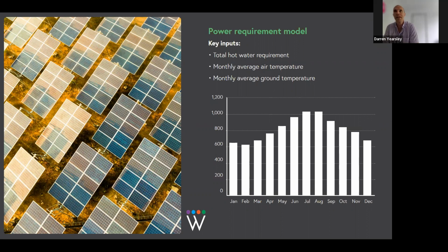So there's a scale in between depending on the quality of the building, the level which you're trying to achieve. Once we get the occupancy and the total number of litres per person, we design the system so that we can shower everybody in the building over what we call the peak period. When we're talking about multi-unit residential, typically you have 2 peak periods a day. You'll have a peak period which runs from 7 a.m. to 9 a.m. and then another one in the early evening, maybe 6 p.m. to 8 p.m., about half the size typically. We will size the system so that we can shower everybody in the building during that first peak period.